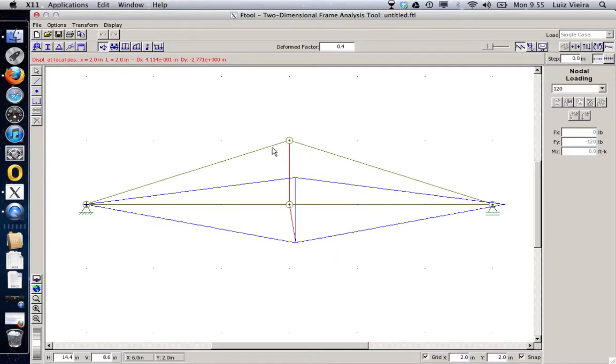One thing is that we are modeling now just one plane of the truss. When you're going to test, you're going to have 2 planes, meaning that this is the sum of both planes. In here, 2.7, if you have another plane with the same truss and same material, same cross-section, this will be divided by half, and you'd be under the 2 inch limit.